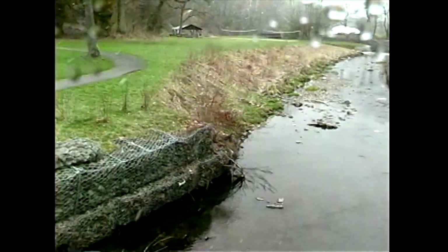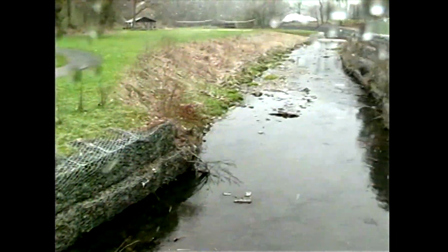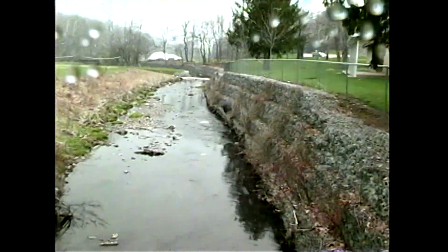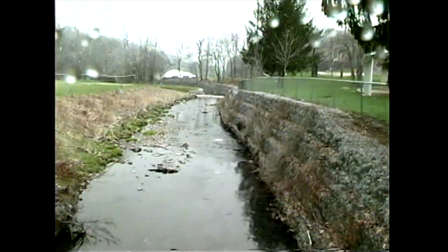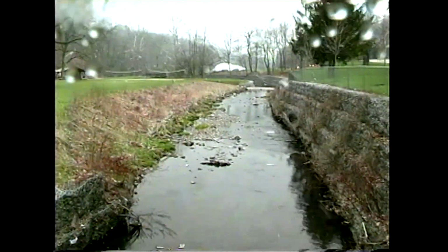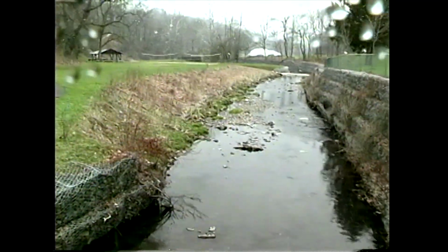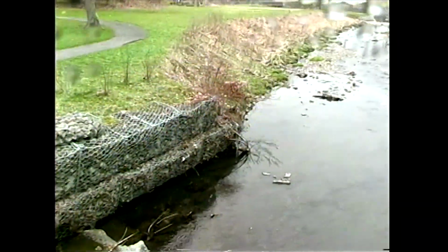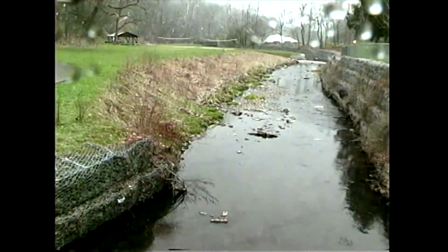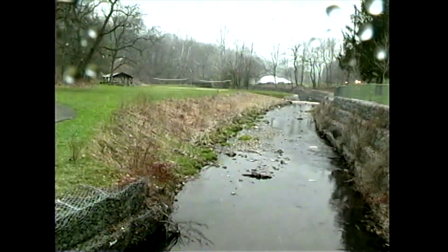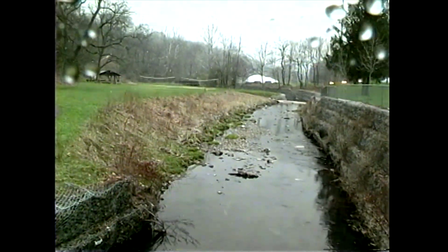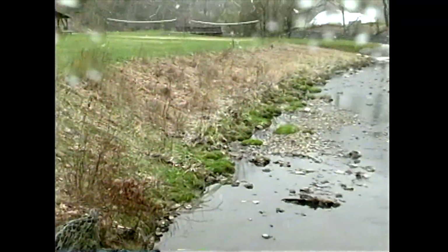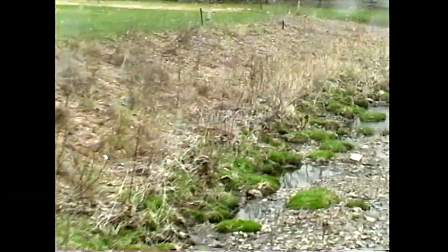And here's our first project area, or the first part of the project area. Before we did this project, you had an unvegetated slope that was very steep, and it was eroding tremendously. Well, as part of the design, we cut back the bank so it was more like a 2-to-1 or 3-to-1 slope, which allowed the vegetation that we planted to colonize and stabilize and help to protect the area.